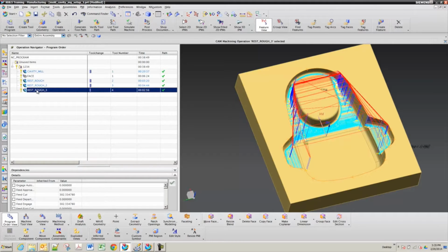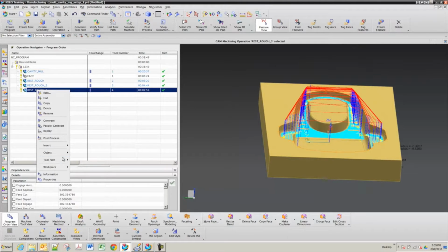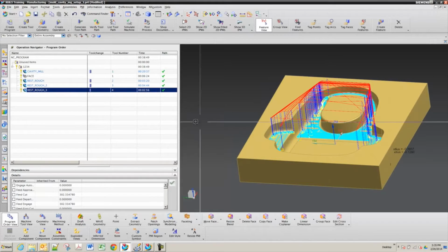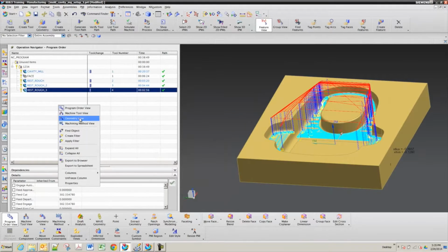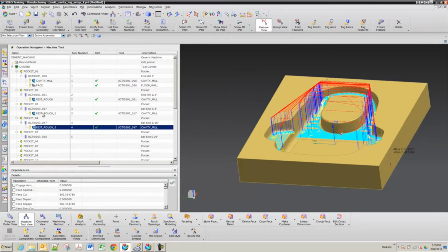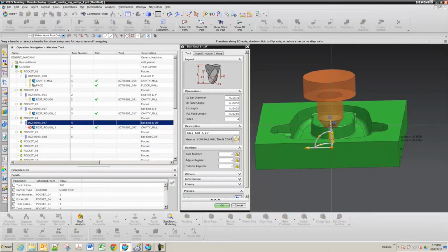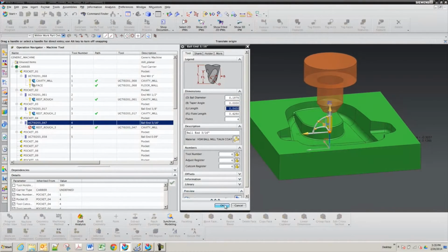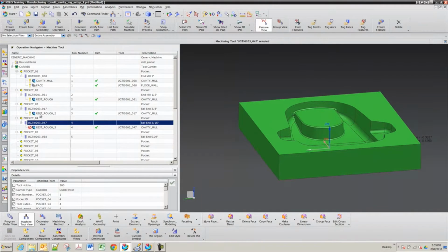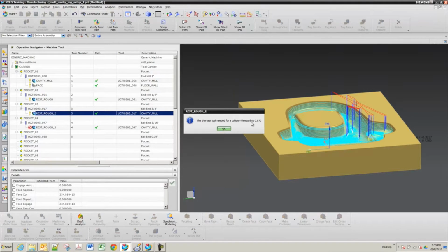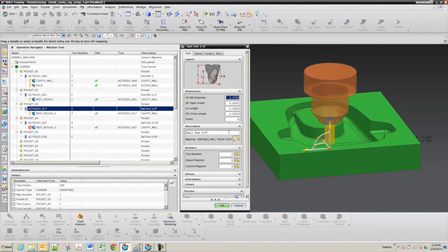On the rest rough 3, I was going to right click and see what the shortest tool is. Report shortest tool. It's saying 831. I can't remember what length we are. Tool. I think it's, yeah, not long enough, so 840. Yeah, so it wasn't long enough. What's this one? I think I already did this one. 870. No, I didn't.